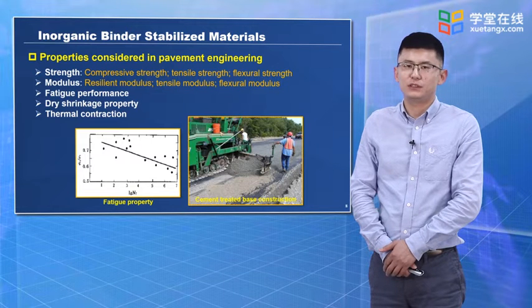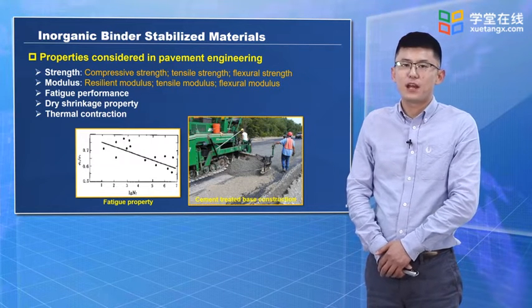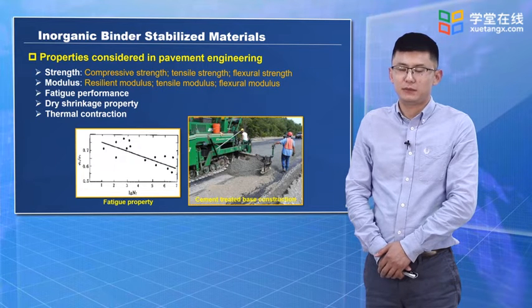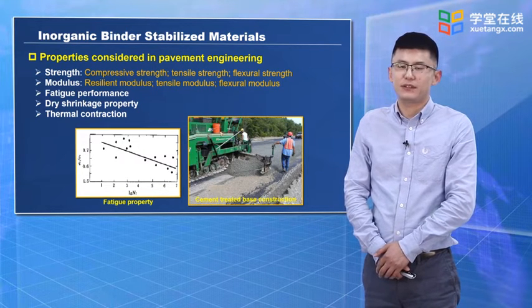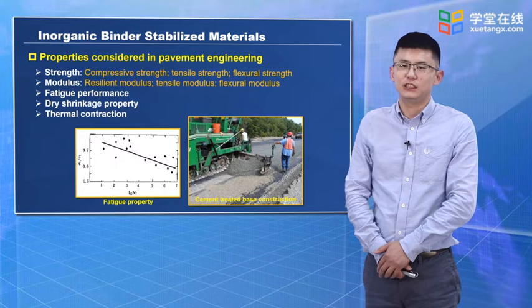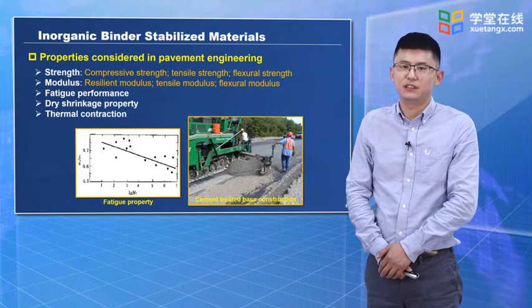Fatigue performance is very, very important because, as we mentioned before, the inorganic binder stabilized material is widely used in China, and it is also the main base type in China's highway system. And one design parameter is based on the fatigue performance of the IBSM.